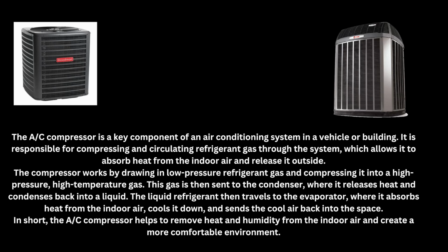Trane actually runs their own compressors, but these units today run what's called a scroll compressor. Back when I started, HVAC systems had what were called pot compressors, which means it had a piston driven up and down in it, just like in a motor vehicle, and it would operate and compress just like that. It had its common, start, and run on it, like it normally does.